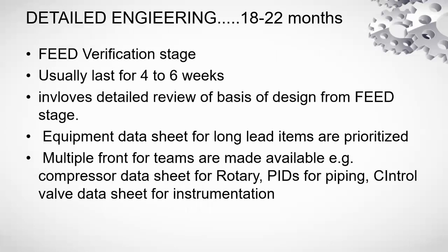Now we are talking about the detail engineering stage on this slide, and the detail engineering stage usually lasts, again depending on the size of the project, for 18 to 22 months. So this detail engineering stage nowadays usually starts with the FEED verification stage. This FEED verification stage lasts for 4 to 6 days, and it involves a detailed review of the basis of design from the FEED stage. Most of the time, this FEED verification is focused on the process engineering aspect.